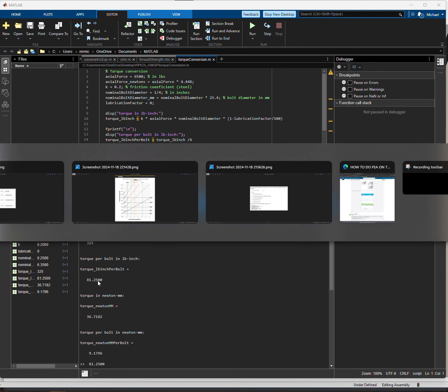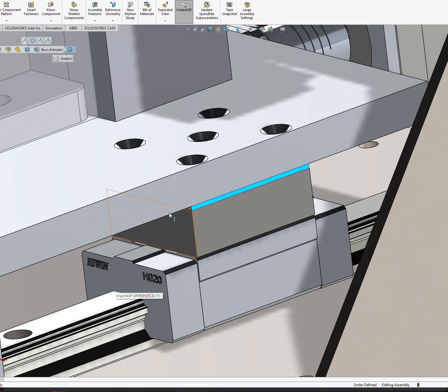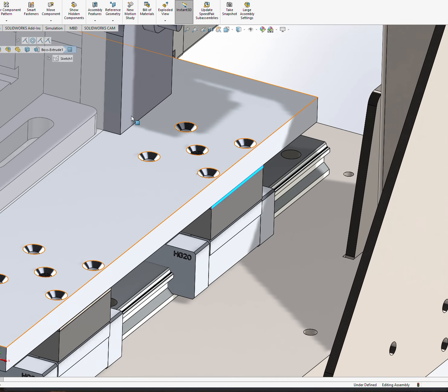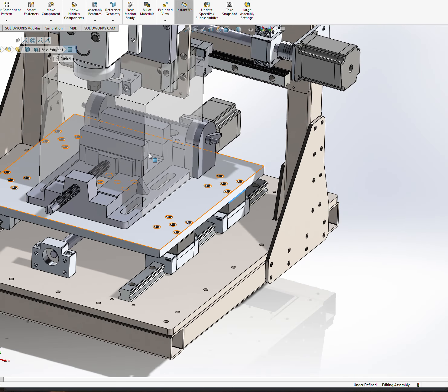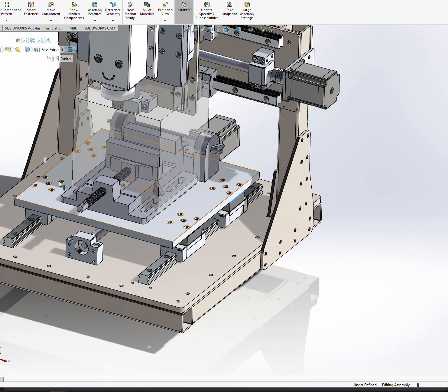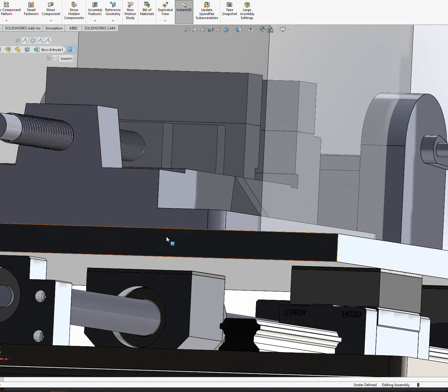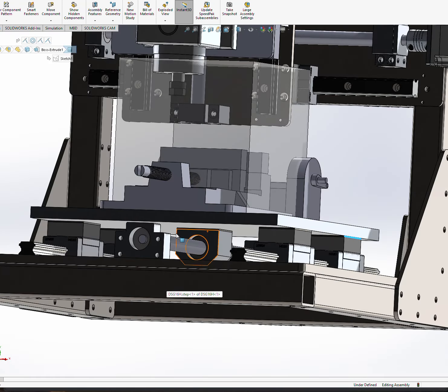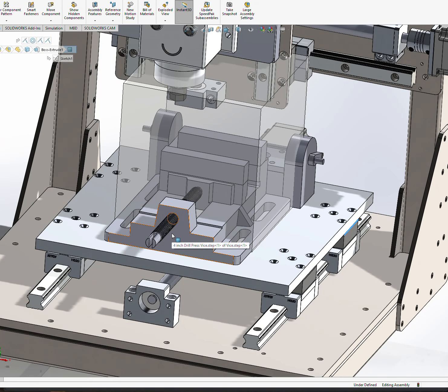Okay, that's 50 times 4. We have 50 inch-pounds on all 4 of these. That's 200 inch-pounds of torque, which is significant. But we also have that being applied at 1, 2, 3, 4, and then under here, 5 different places. 200 times 5 is 1,000 inch-pounds of torque, making this plate hold on to the rest of the machine.